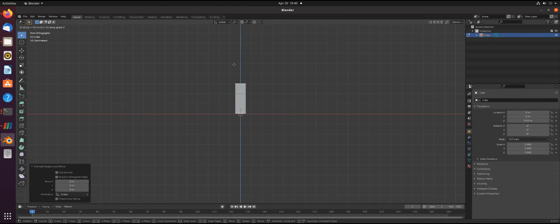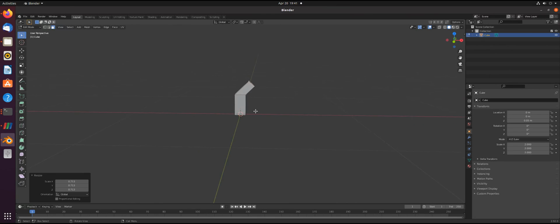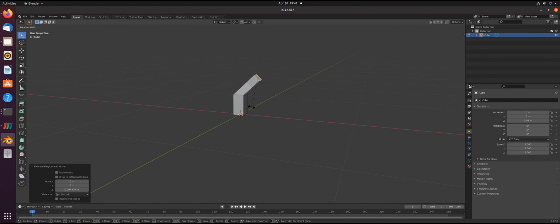With the key E, you can also extrude a selection. I will model a chimney above the reaction chamber I created. This is just an example of how you can model an STL structure without having access to a commercial CAD program. If you have access to SolidWorks, Autodesk Inventor or similar programs, you can use them as well. However, the meshes created out of them are usually not ideal. How to solve issues with the STL mesh I will discuss later.